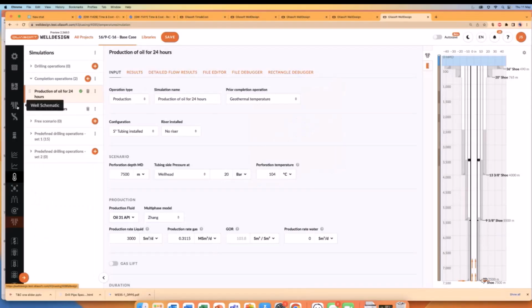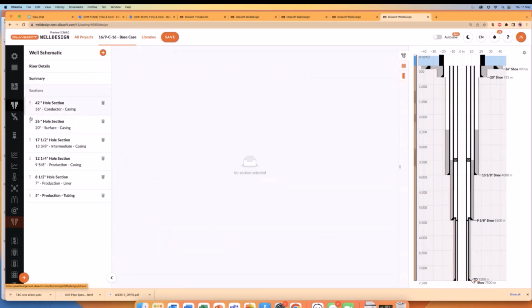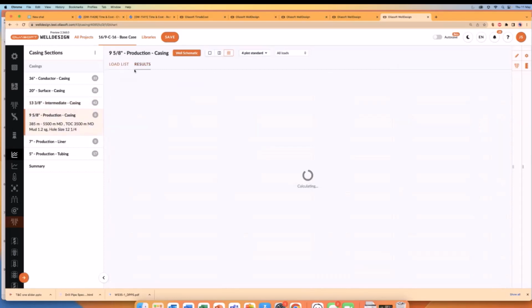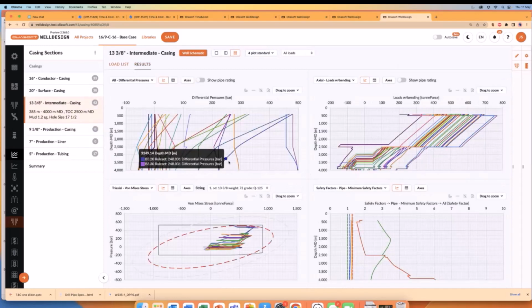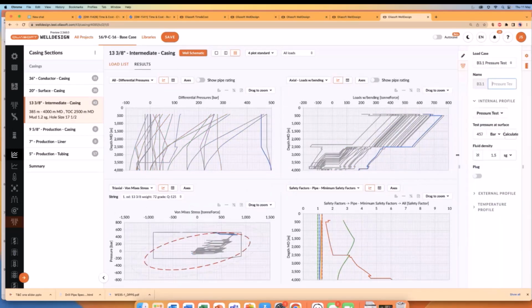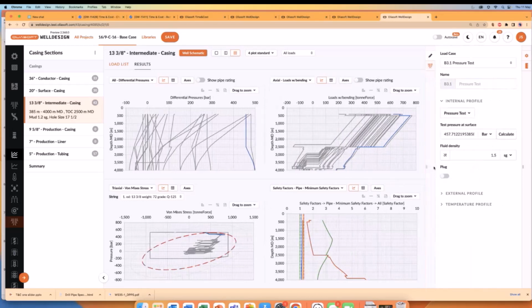So tubular design, for example, in Oliasoft is very similar to something like WellCat, right? You will go in and define lots of load cases, and you would do some thermal simulations and link those into load cases and so on. All of that stuff is quite labor intensive. It takes a long time just to define all of the loads, right?